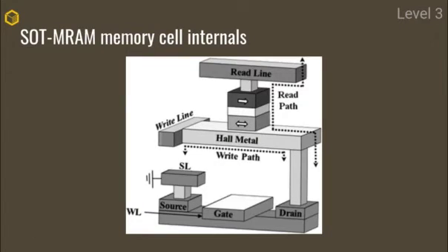And so we can see it as a switch for giving us either positively polarized electrons or negatively polarized electrons. So how are you actually going to use it? Here you might remember I have my cell, so I've got my fixed layer and my free layer, and here I've got my metal, and I'm going to switch the direction of my current flow through this heavy metal, based on the polarization I want on my free layer.